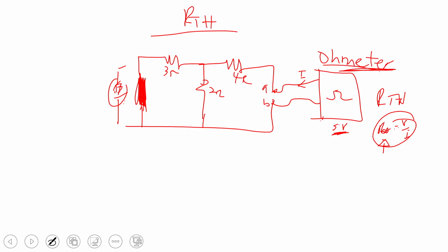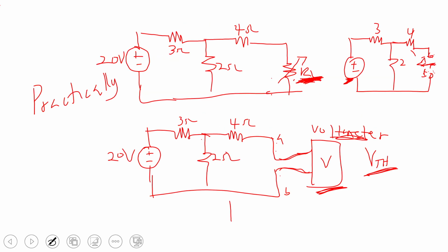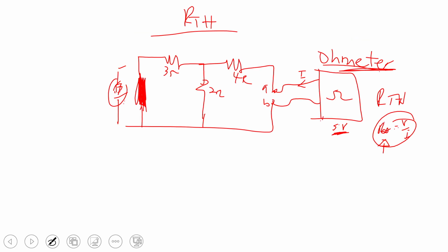before you measure the resistance. So in summary, like your house case, let's say it's a bulb, and you are interested in finding the current in that bulb. All that Thevenin is saying is to remove the bulb. After removing the bulb, take a voltmeter, measure the voltage where the bulb was, and call that voltage Thevenin's voltage. Afterwards, take an ohmmeter, but make sure that you switch all the lights in the room off. Switch everything off. Take all sources away before you put an ohmmeter to measure the resistance, which we call RTH.